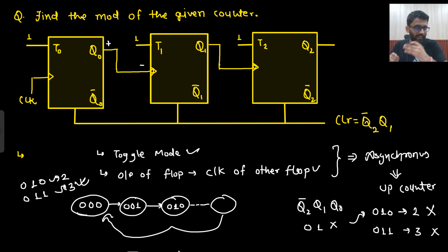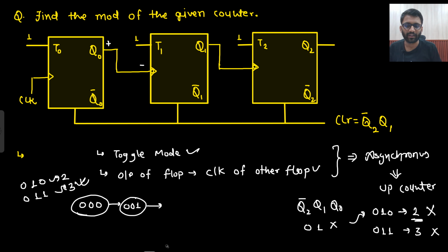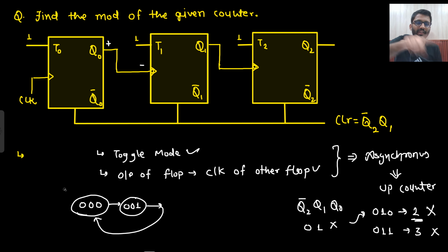And in this case, you are starting from the bottom, 0, 1, 2 number cannot be there, because at 2 only it is certainly cancelling. So 2 number can also not be there. So only this loop will be there. There you go, this loop. Okay, so in case of up counter, you will always take the minimum value. In case of down counter, you will always take the maximum value.